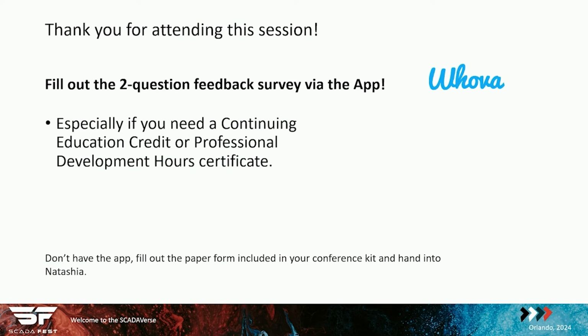One of my first questions is, do any of the brokers for Sparkplug B support any form of failover redundancy? Yeah, the protocol supports that itself. I didn't go into that in great detail. The protocol defines that you would have a redundant broker, so basically two brokers would exist in your system. And what the SCADA host does is it publishes to the broker it's currently listening to an ID that says, yes, I'm online.